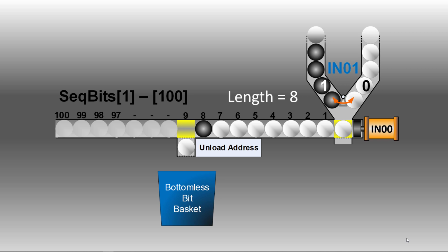So what we did is we created a 100 element array of Boolean. Now, Booleans, those are bits. Unfortunately, a Boolean data type uses more than that amount of memory. In the 5000 platform, and of course in the 500 you have no Boolean data types, but in 5000, a Boolean data type uses 1 bit of the native data type, double integer.